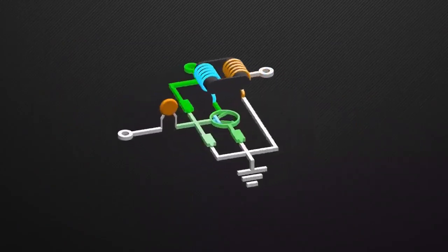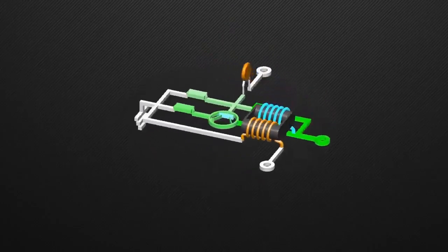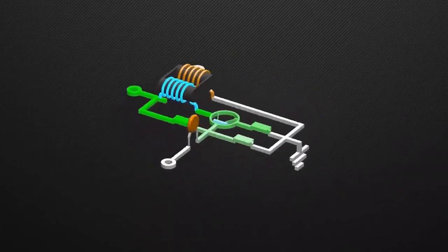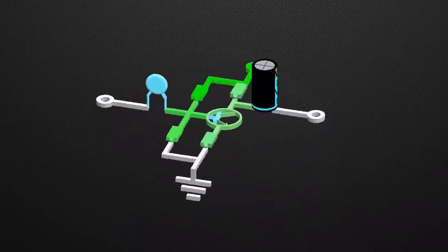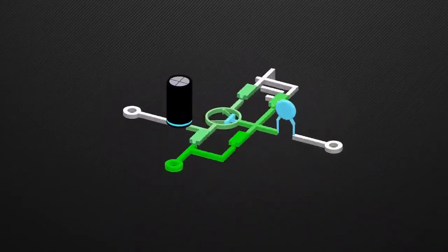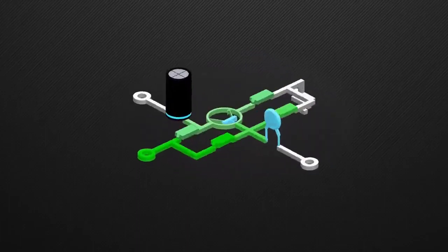However, the transformer is an inductive device due to its windings and core, so using inductive components in amplifier switching circuits is best avoided, as any back EMFs generated may damage the transistor. A Class A amplifier can reproduce full waveform, with very low distortions, but as the transistor is biased, it's always on. This and some other factors reduce its efficiency to less than 30%, which is very low.